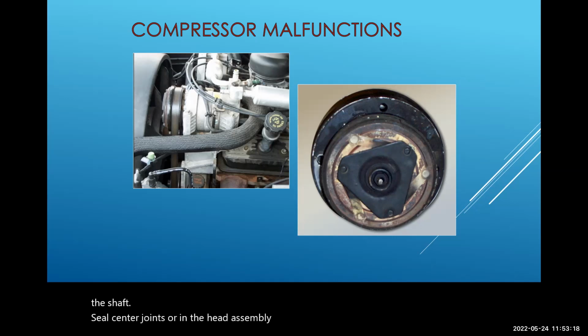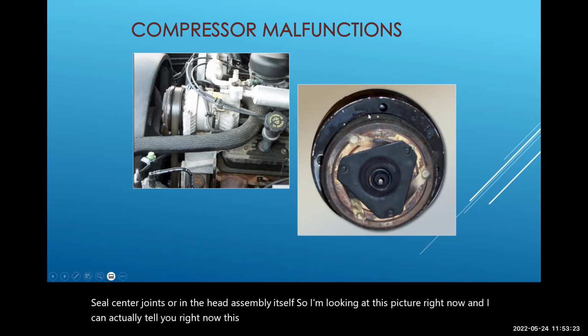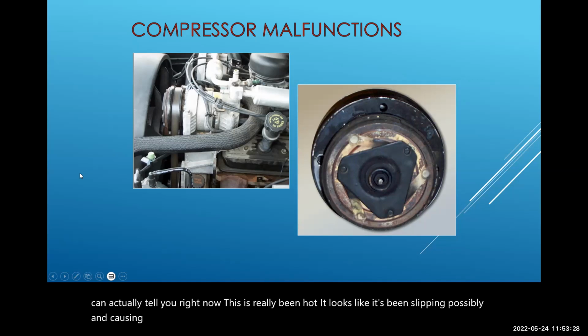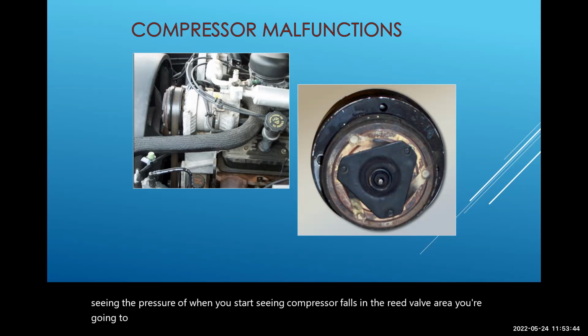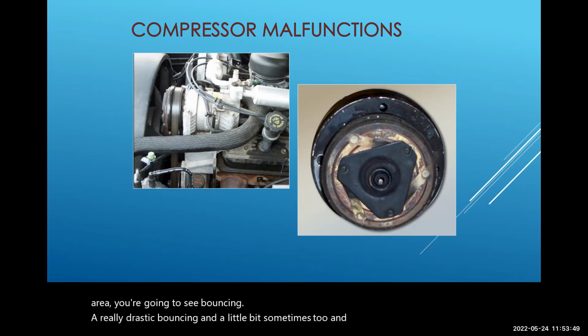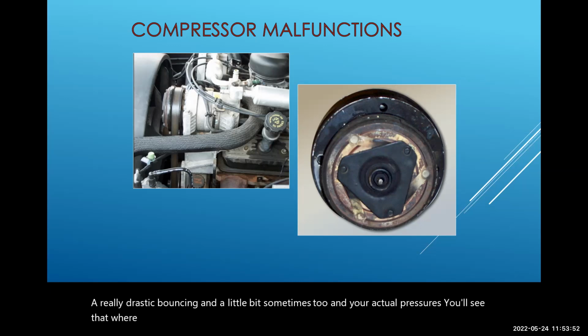I'm looking at this picture right now, and I can tell you this has really been hot. It looks like it's been slipping, possibly, and causing heat. But the other thing I really look at is your pressures. When you start seeing compressor faults in the reed valve area, you're going to see really drastic bouncing, and sometimes a little bit, in your actual pressures. You'll see that where it's not sealing properly. So you can have stuff like that.